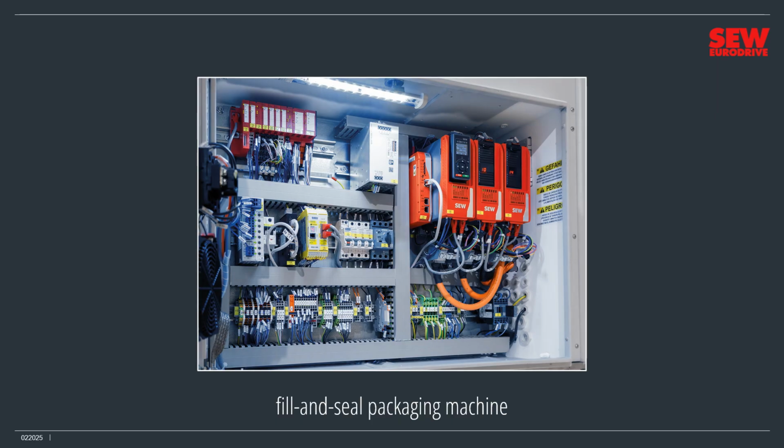Let's look inside. The small SEW Eurodrive controller orchestrates every machine operation. It manages the three servo gear motor drives through their attached MoviTrack Advanced VFDs. The controller has no built-in I/O, so it connects to the machine's many I/O devices through multiple I/O modules. These can handle simple digital devices like buttons and sensors, but they can also control more complex devices like the stepper motors, which have built-in encoders. Although it's a little hard to see in the picture, a field bus links everything together, including the operator control HMI. Pretty nice.